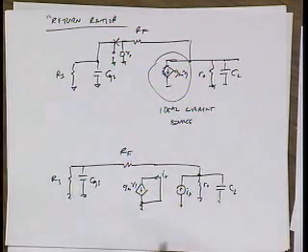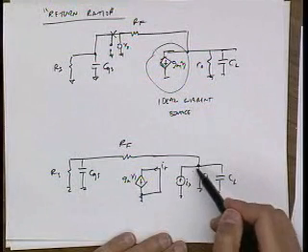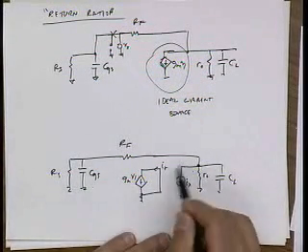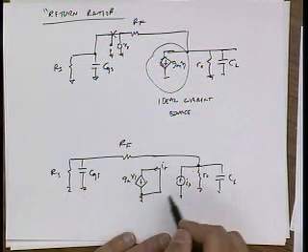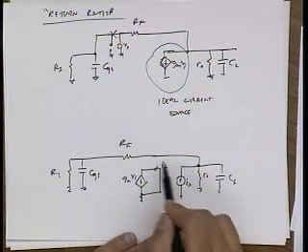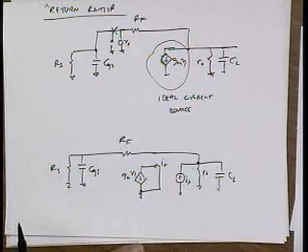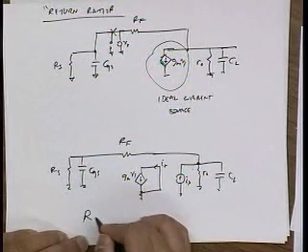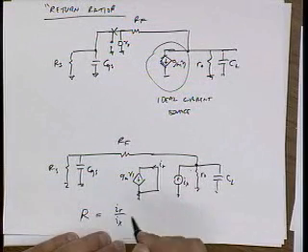Okay, so notice now, as far as the rest of the loop goes, it's still driven by the same kind of source. It's still driven by a current source, infinite impedance, and as far as this current source is concerned, it doesn't care less, right? So I just short it and observe what current flows in it, right? And that's my return signal. So the loop gain, actually people call this the return ratio, but it's just the loop gain, is IR over IX.